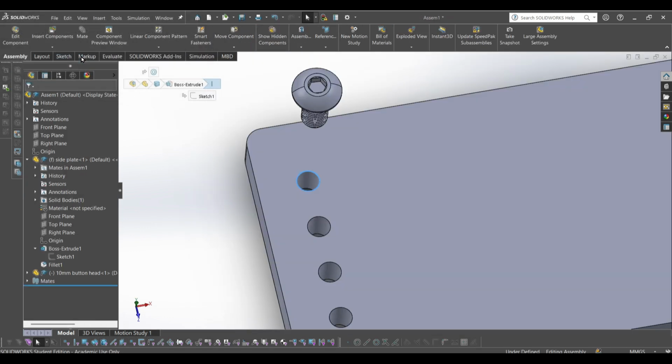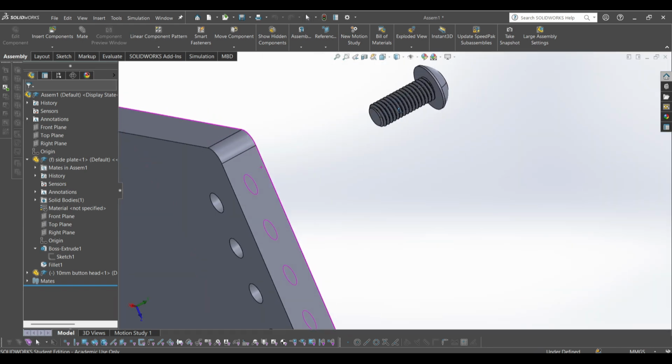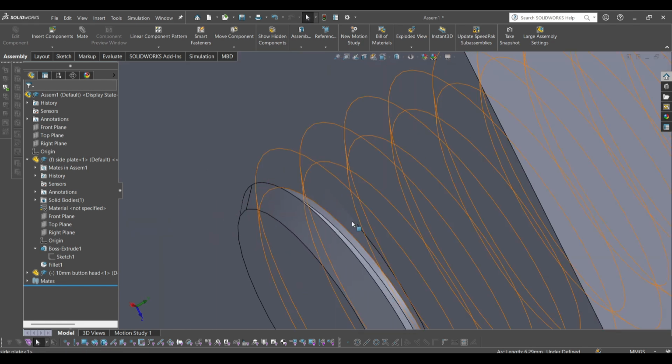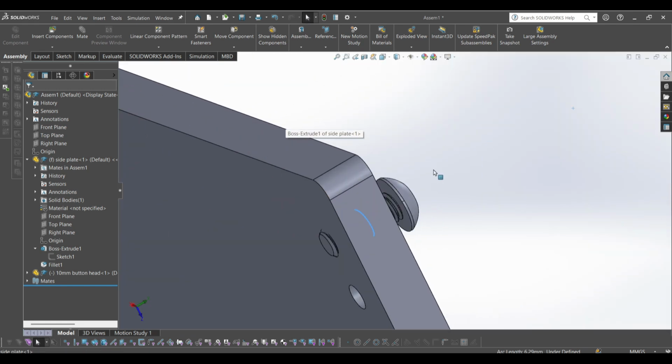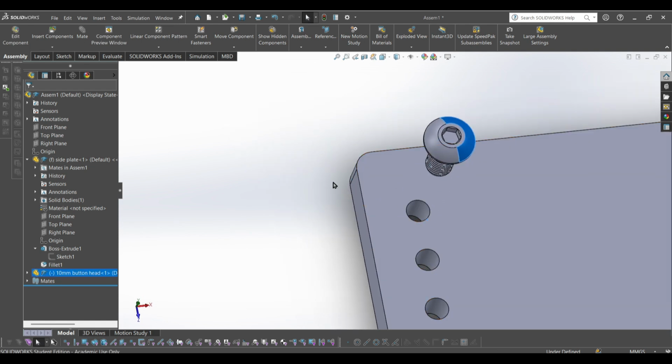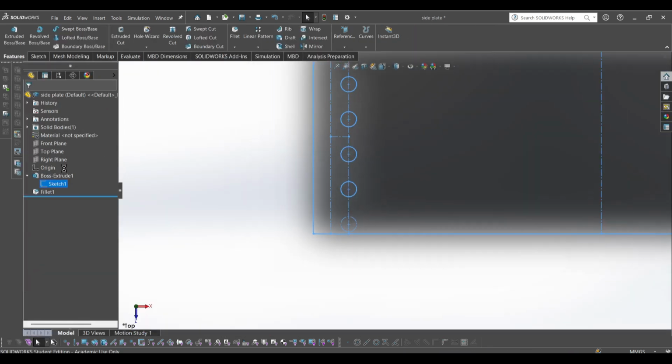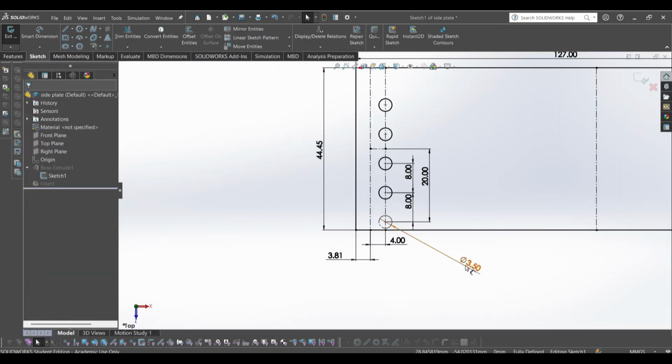So we're going to go back here, click yes, and we can see that our screw doesn't fit through the hole properly. So if we had the plate with the hole of exactly 4 millimeters, when it actually gets printed, the screw wouldn't be able to go through all the way. And that would cause issues with assembling whatever you're trying to assemble with the plate.